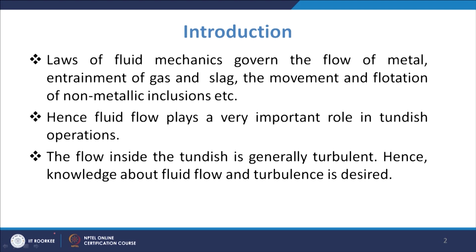So, in the tundish you have different regions. There is a region where the liquid metal is coming from the ladle, and then you have the remote regions also. In most cases, generally the tundish flow is considered to be turbulent.